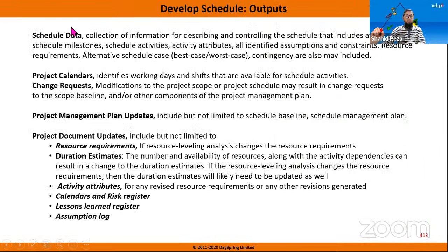All right. Schedule data is the supporting data. Why each task has this much time or this many days, those supporting documents, supporting information to capture, that is known as schedule data. And project calendar. So when you are making the final schedule, you have to use project calendar. I mentioned this. Project calendar means what are the holidays, what are the weekends, and what is the working time of our office for this project. So that is known as project calendar.